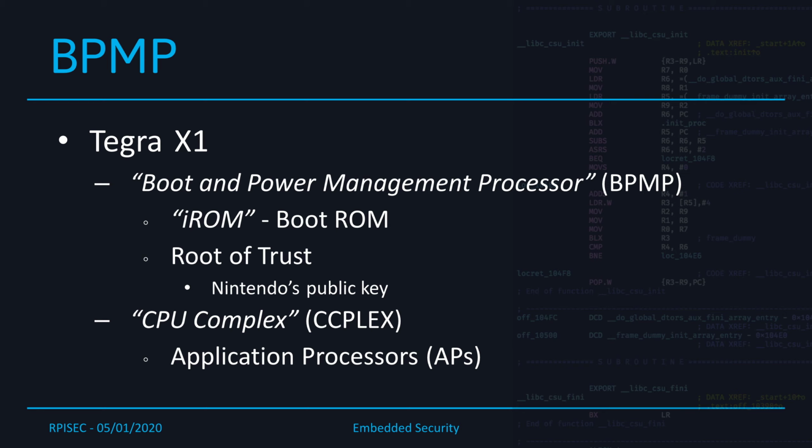They're not real fuses, but in an embedded context, a fuse is basically a region of memory that can be written to once ever, and usually this is at the factory, and then you can normally not rewrite these regions. There's a separate thing that you basically use to seal them. So the public key is written in at the factory, and you can't ever change it.